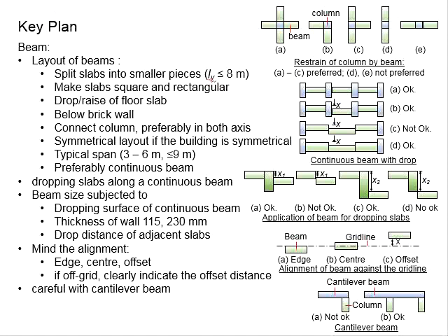To ensure the stability of the column, we will need the column to be restrained in both directions, the x-x axis and the y-y axis. The beam will serve as the restraint to the column in reducing its effective length, which will directly govern the slenderness of the column, and this will significantly influence the amount of reinforcement bar required in the column.